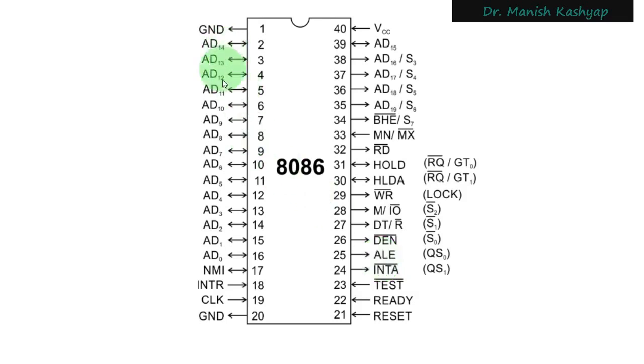So this is the direction of the data flow. Up to the point wherever your data bus is multiplexed with the address bus, these are bidirectional pins because data can be taken from the microprocessor and can be sent to the outside world also. However, the remaining pins are unidirectional only, right? Similarly, you can look at other signals also, and justify for yourself why the direction is outwards or inwards, right? So this is a more clear diagram of what we saw last time.